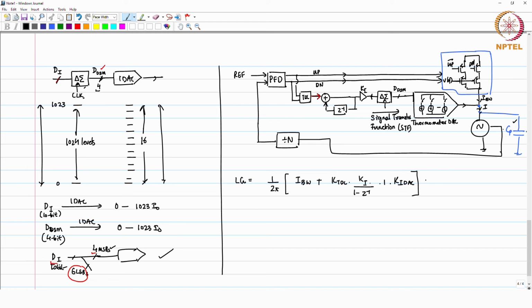So, you can say this current goes through this oscillator and the capacitor, which is R VCO in parallel with 1 over SCp, to give you the control voltage whatever you have at VDD oscillator, and then from that voltage to output frequency we know it is K VCO over S, times 1 by N.